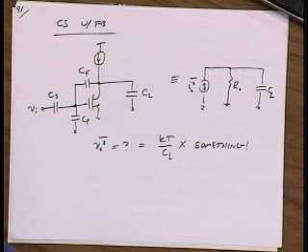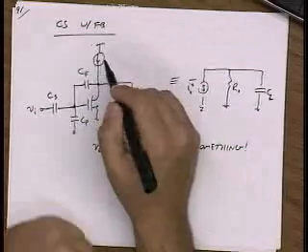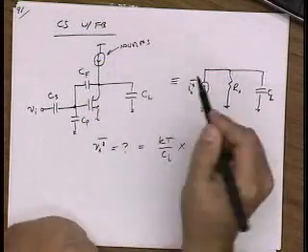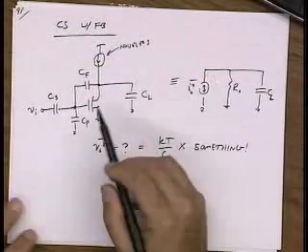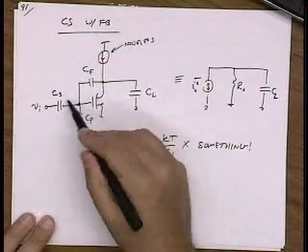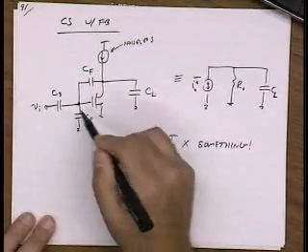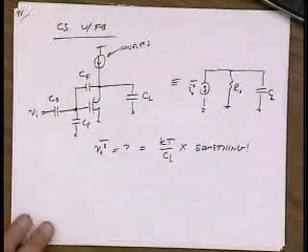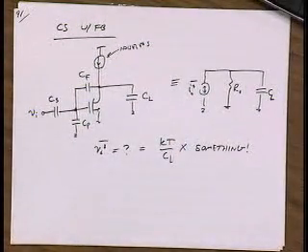Well, let's take an extreme example. Let's say that this is noiseless, just for simplicity. And let's say your feedback factor in this amplifier were equal to 1. In other words, these are very small capacitors, and this is a very large capacitor. So most of the signal just feeds back, and you have a feedback factor of 1. What would that something be in that case?